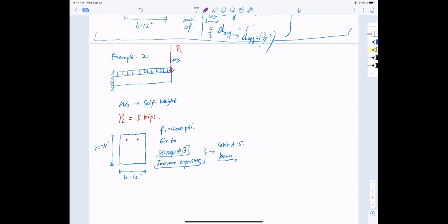So the thing is, think about the bending moment. If I'm pushing the beam down like this, can you imagine, my bending moment will be negative. Is that right? Yeah. Okay. So if the bending moment is negative, which part would take care of tension, top or bottom? At the end section right here, bending this way, you look at the arrow. It's like pulling things out and going to compress it here. So which side should see tension, top or bottom? Top. There you go. Thank you very much. So that's where the tension is, and that's where my bar is going to be.